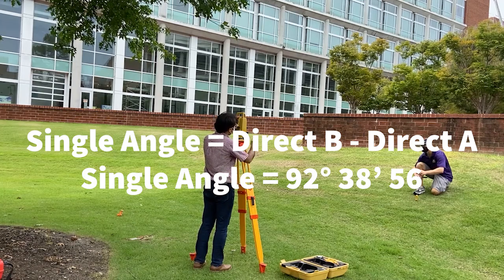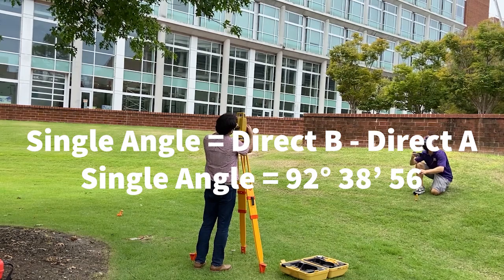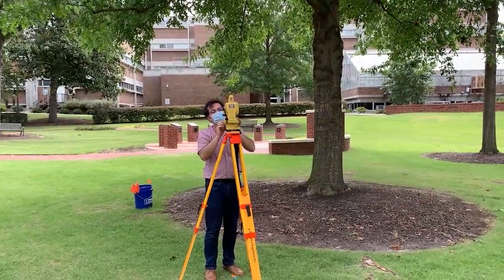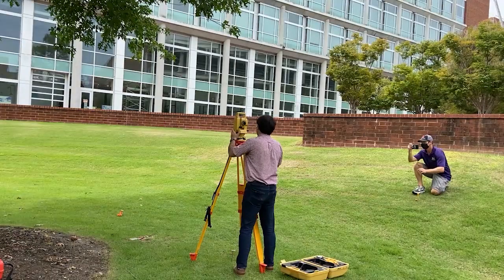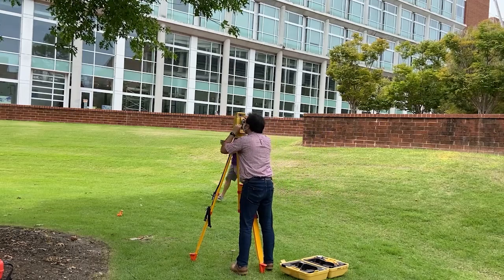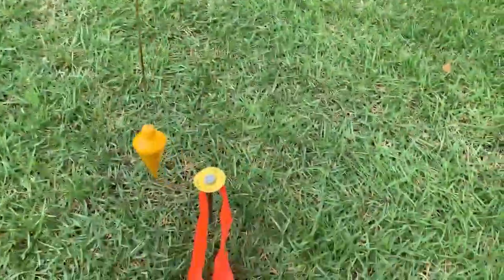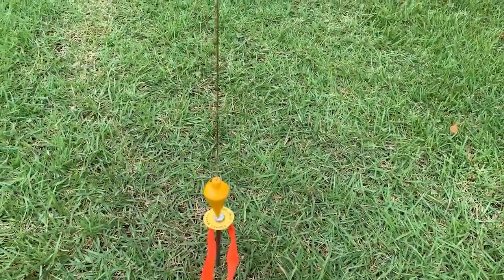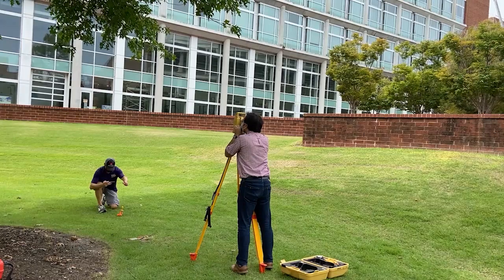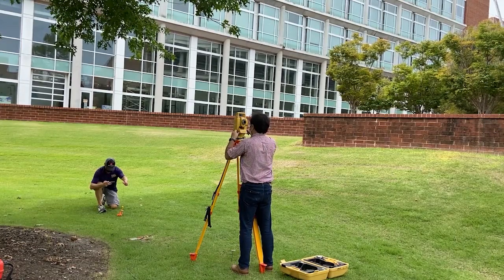For double angle, I need to flip this telescope 180 degrees, then rotate, and shoot to the first point again. Once it is in place, I lock this.